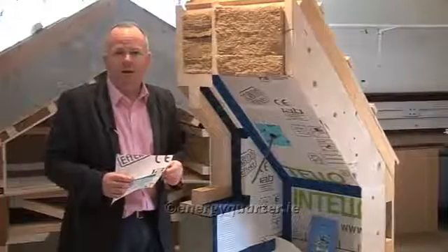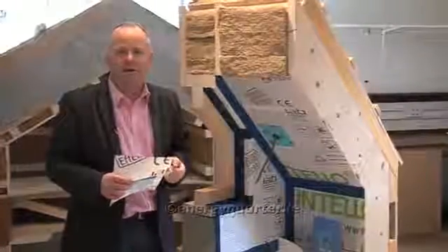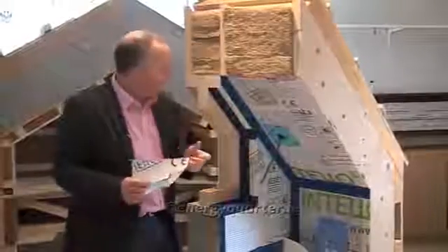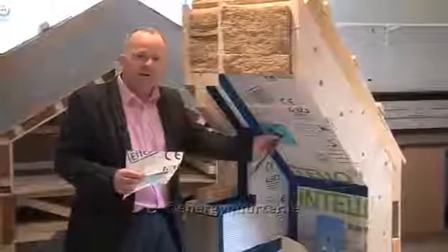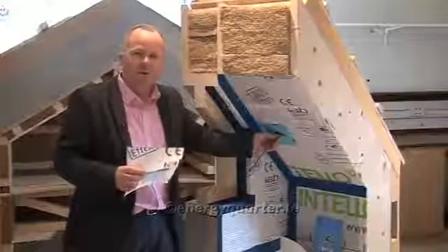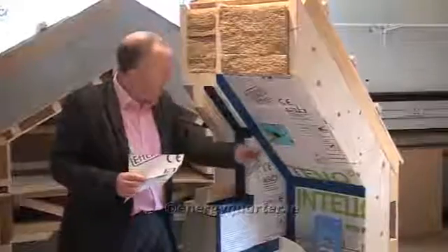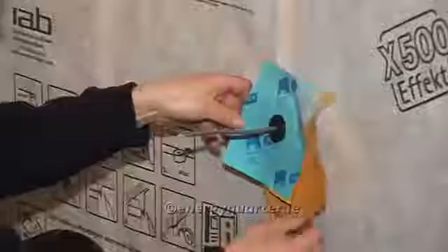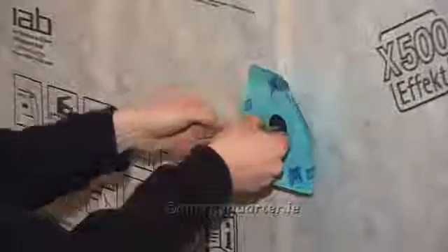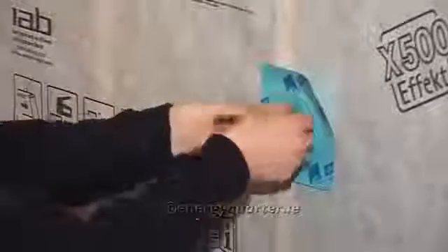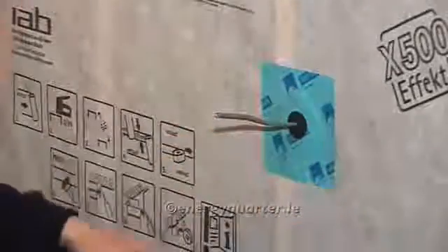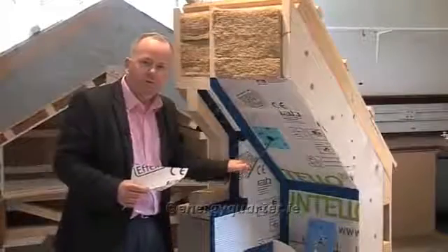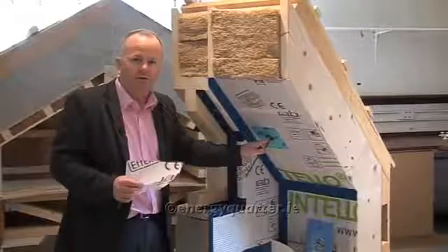Another problem we can have in terms of airtightness is where we're putting services through the building envelope. So whether that's waste pipes or wires or whatever. And you can see here again that the manufacturers of these products have come up with very high quality proprietary products. So here we have a cable, let's say it's for a light switch or for a socket or something like that, and it would puncture the airtight membrane. So we've got a special rubber diaphragm on this which keeps this airtight and prevents any cold air coming in, but it also prevents any humid air getting into the timber frame structure, which could be a problem down the line.